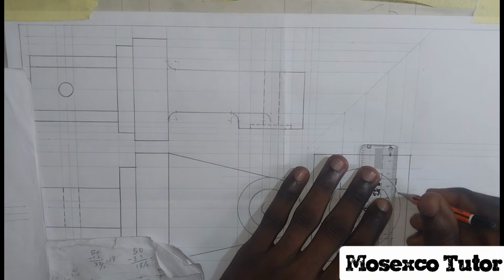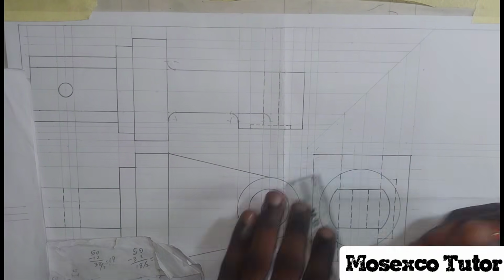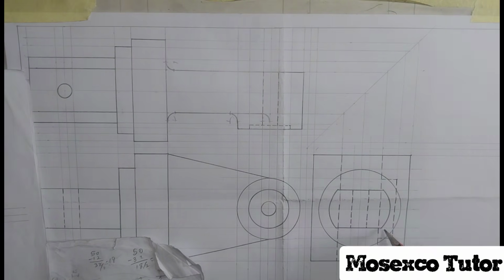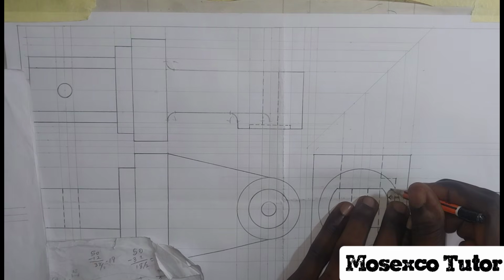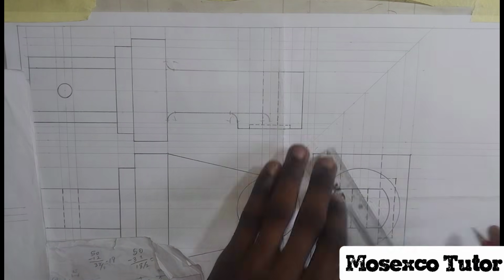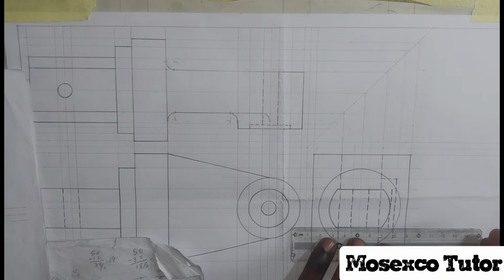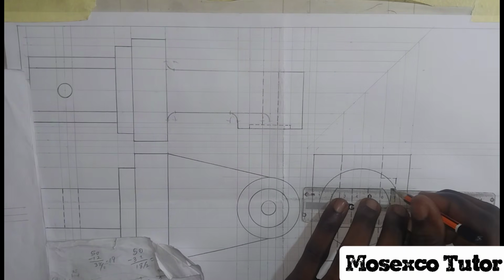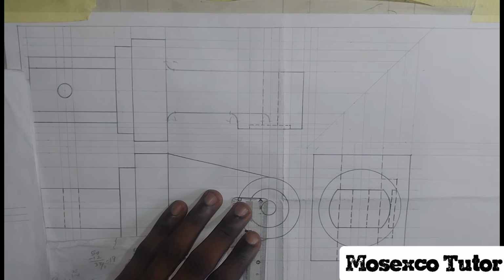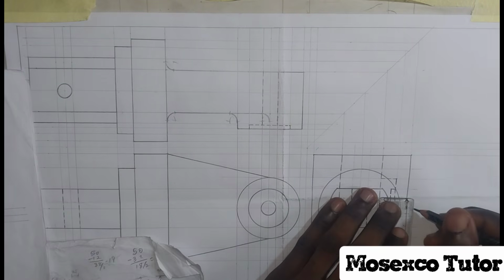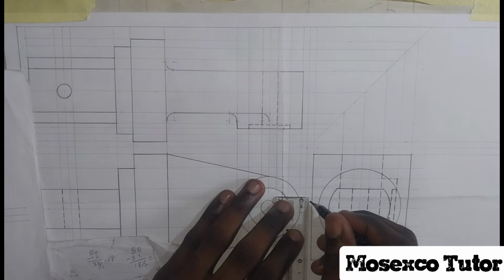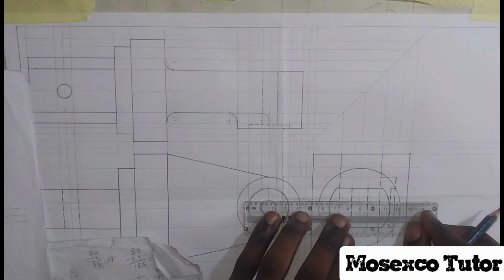That small part, if we should find the distance, 4.4 minus 3.2, that gives us 1.2. So that small part there is 1.2. Then I take 0.3 inward, 0.3 inward on this other line that you have there. I join it as broken line. You can see it's in the same plane with that other line there. So that's what I have here as this.